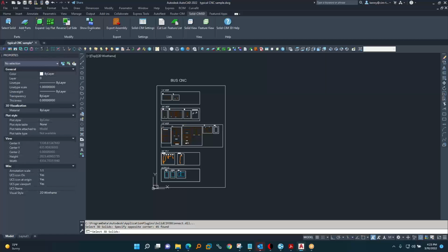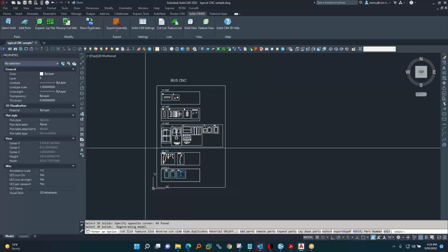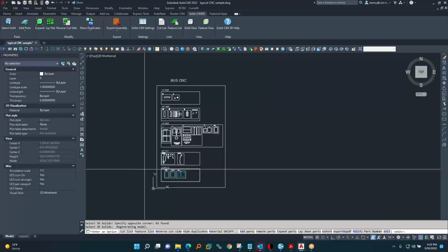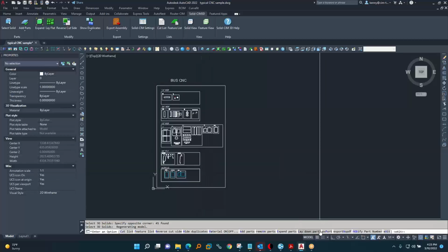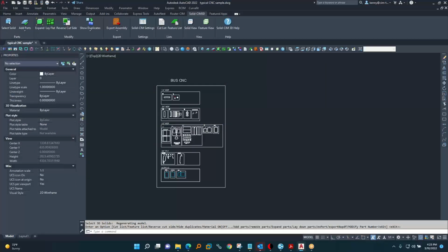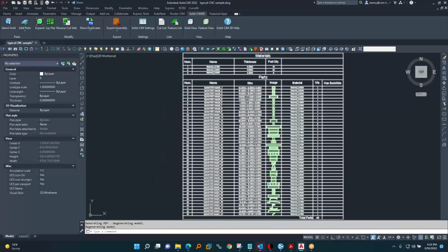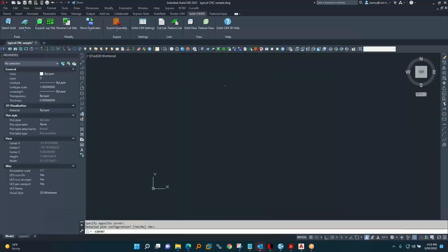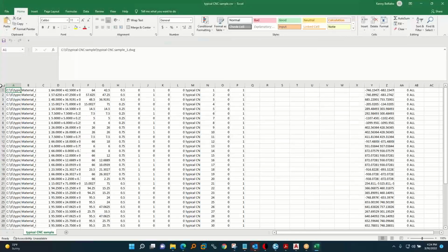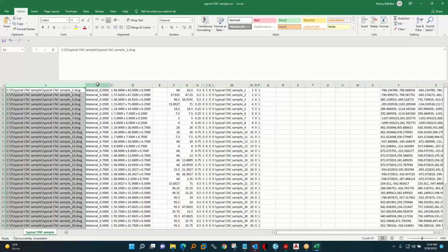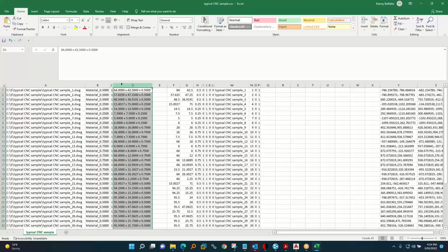That will take the material that you used in AutoCAD, and it picks up part names and label information. Here you could see, let me pick export, and I'll export these parts out. It makes a cut list, and that has all your materials in there. All the parts that were 3D solids are now exported, and it makes a cut list where you have the name of the part, the material, and the quantity, and there's the panel dimensions of it right there.